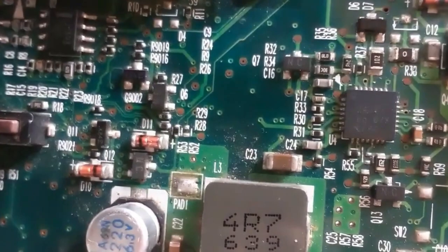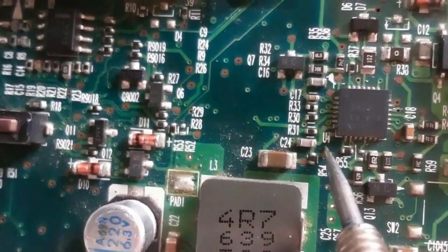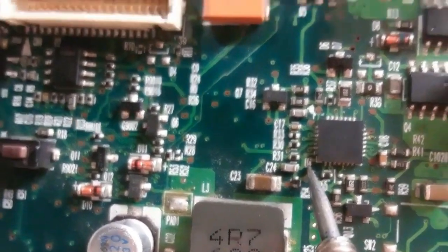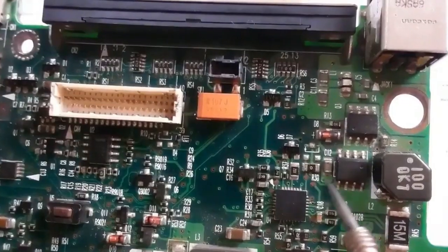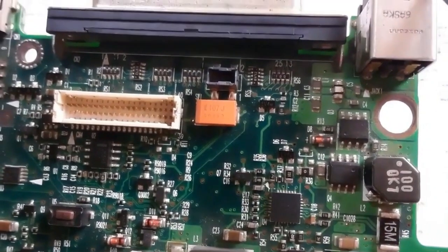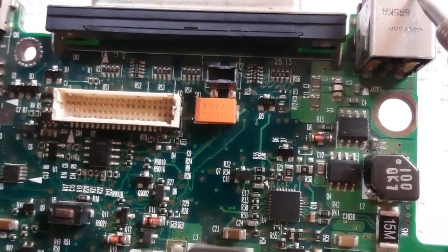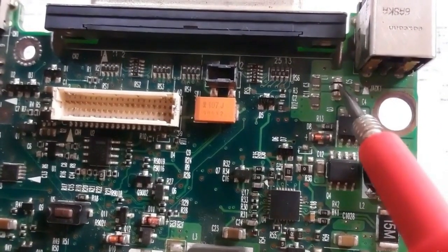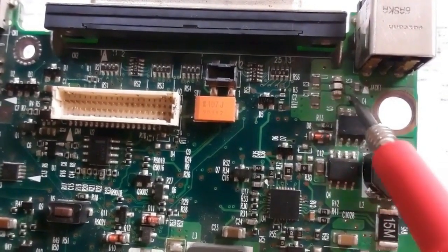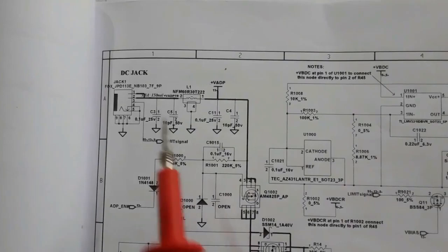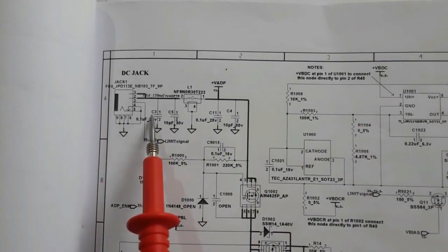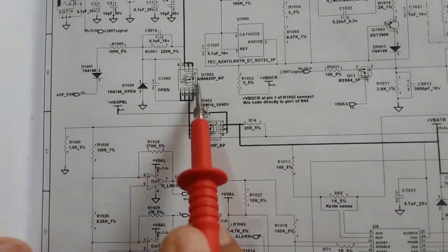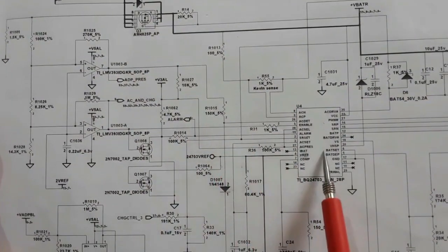So let's check this charge IC in the motherboard. As you can see, U4, the charge IC. Always U is for ICs, Q for transistors. The charge IC is near the power jack. Basically, all the power components are near the power jack. So this is the power jack. Here we have capacitors. This is the inductor. Here we have 2 switches or MOSFETs, and here we have the charge IC.